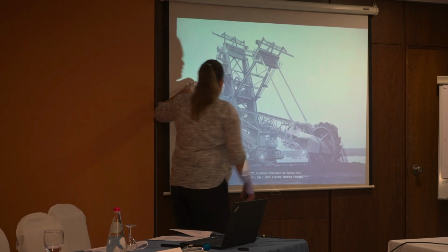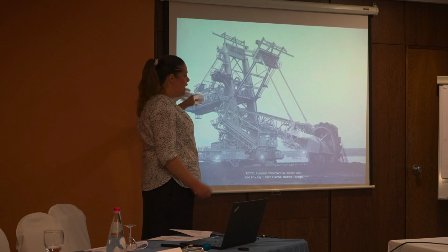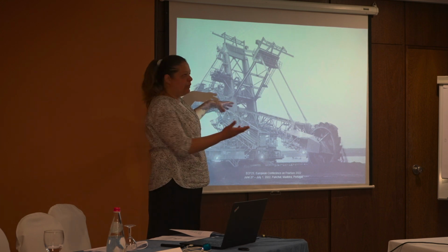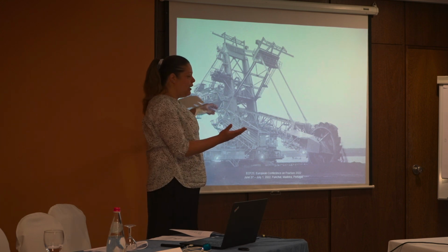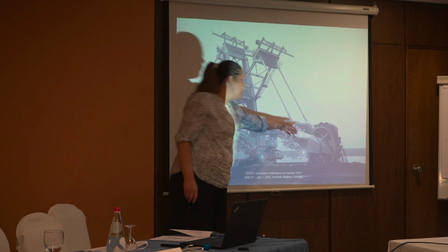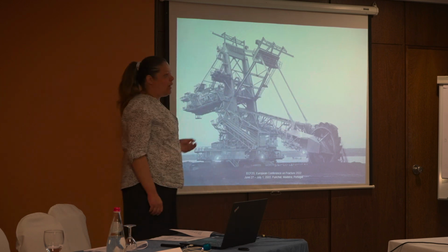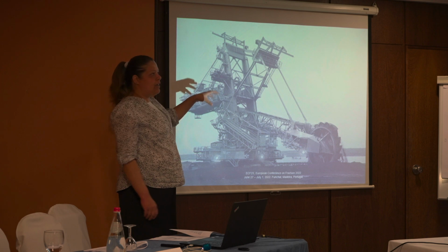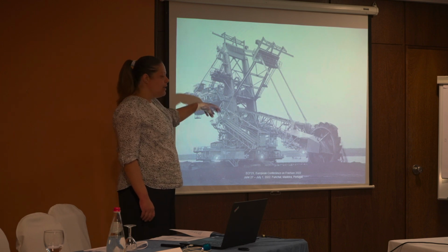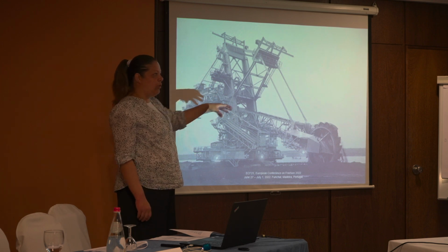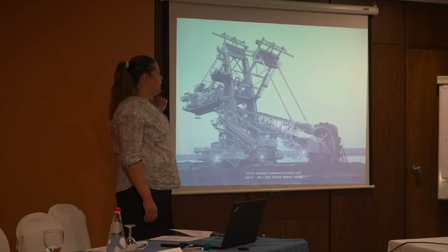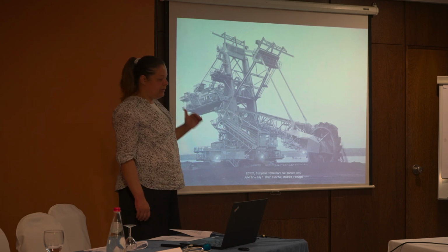You see here 2 large masses, and when the rotary movement is braking, you have inertial forces caused by these 2 large masses, and that could be dangerous for the structure as well. So we will introduce 2 more loading cases, and we will introduce a buckling criterion.